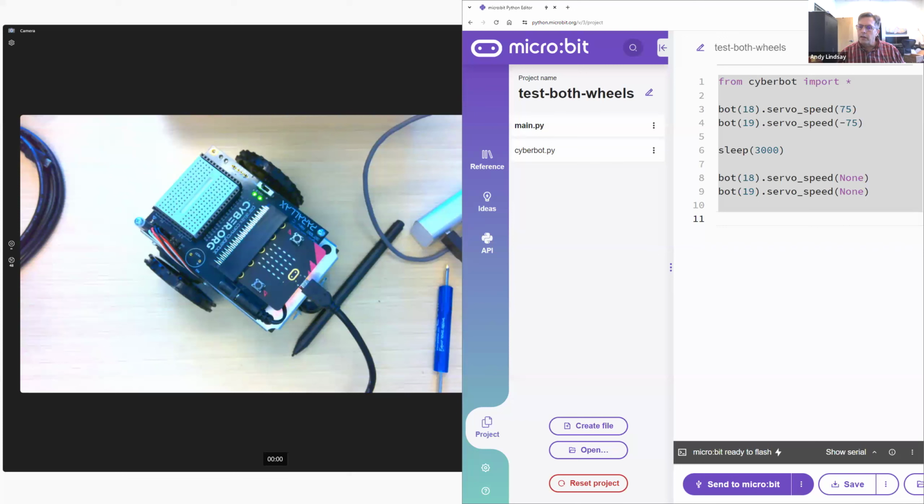Okay, and then let's see. Even if both servos are calibrated correctly, can they still rotate at slightly different velocities? The answer is yes. They're not precision devices, and each one is slightly different. It can be slightly different clockwise and counterclockwise, and also in terms of the internal resistance of the gears and the motor's behavior. That all varies, and so we're going to calibrate in the software.